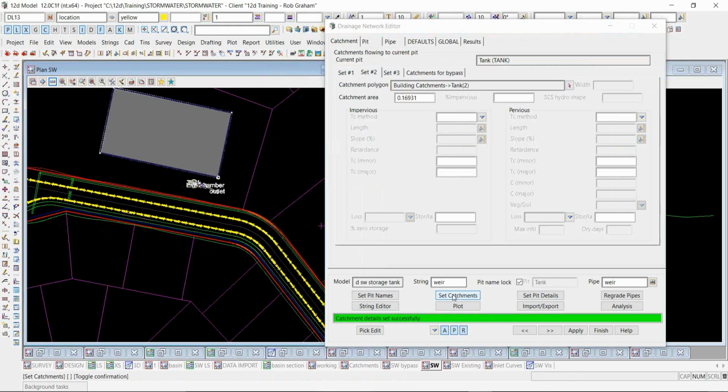A very good answer to that would be "too vague," because it does depend where you are in the world. It depends a great deal on your IFD, the magnitude of your rainfall, but also the temporal patterns, whether the flow is spread out quite a bit over time or if you get very sharp peaks. So really, I suppose the best answer would be "too vague."